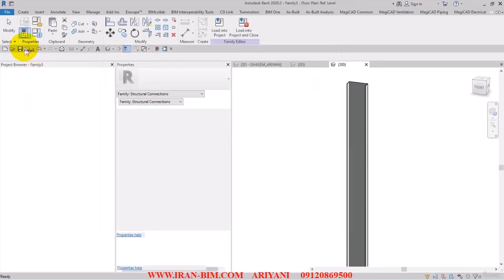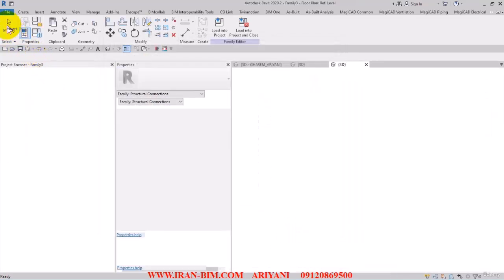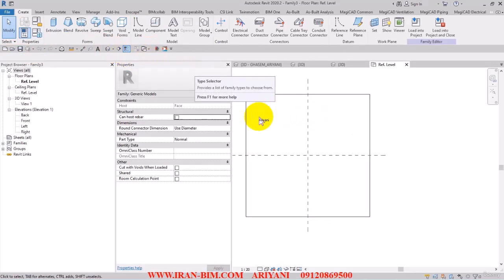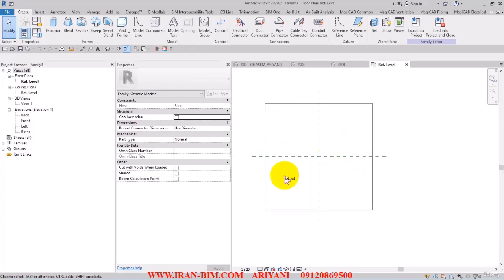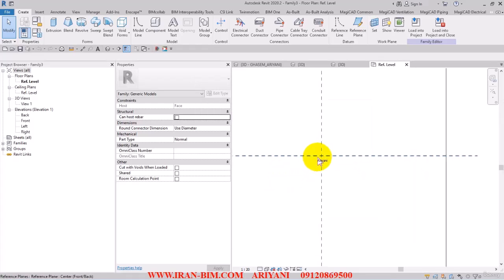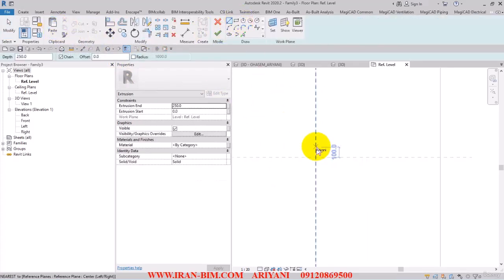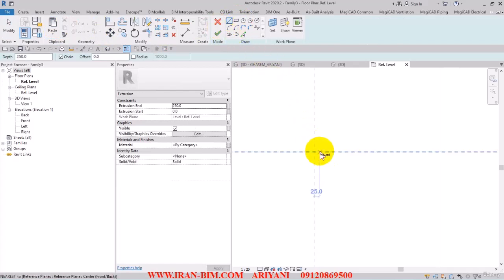Open it up. So it's been loaded up, and there it is. If you pay attention to the shape of it, it has some sort of an L shape, which is important to what we're going to do next. So here, let me go and select extrusion. So for the dimensions here, we have 35 for width and 50 for length.